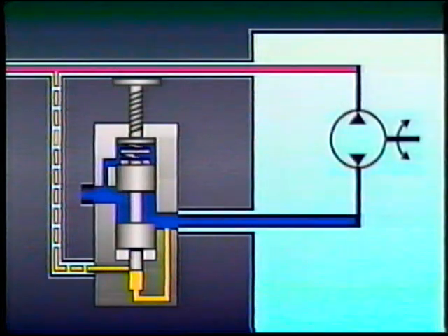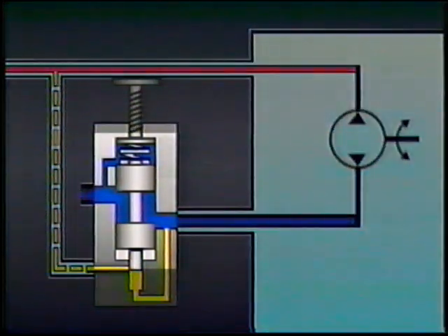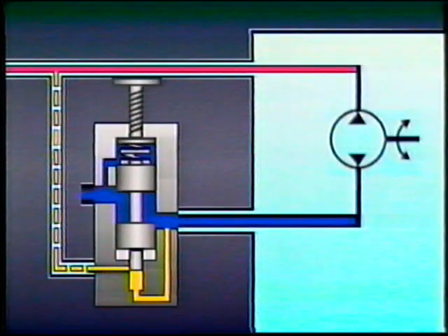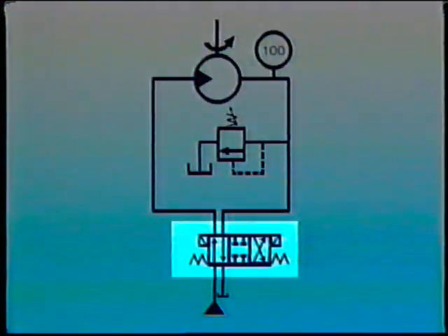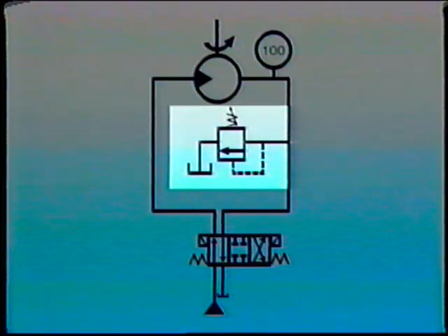A brake valve can automatically apply just enough back pressure to keep a load from running away with the motor, but still allow the motor to develop its full torque. Braking can also be achieved on demand by using a directional control valve and a standard relief valve.